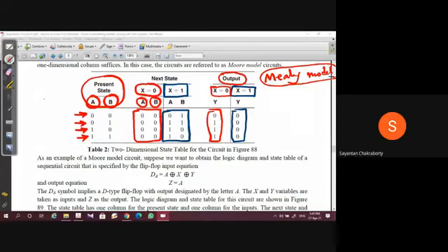So this is obviously not very useful for a Moore model, where the next state or the output is a function of present state only, and there is no function of input in case of output. But obviously the transition from present state to next state will also be very simply put in a concise manner. Okay, that's why the two-dimensional state tables are much more widely used.